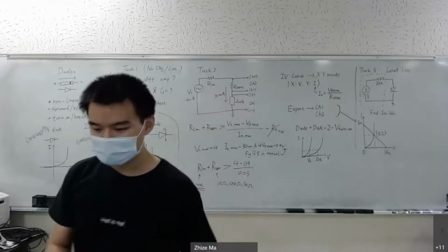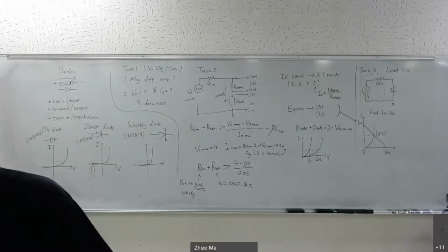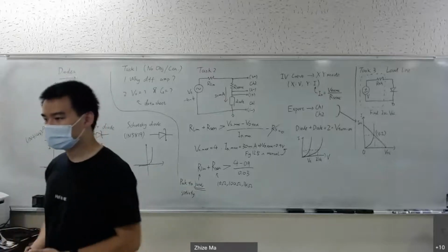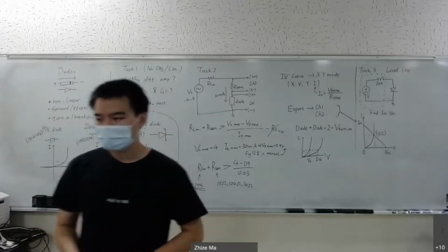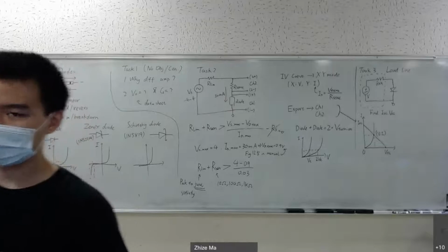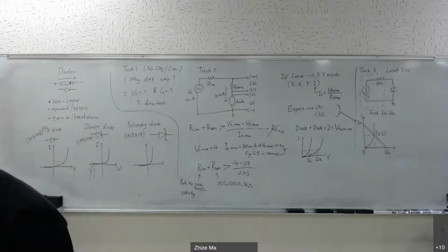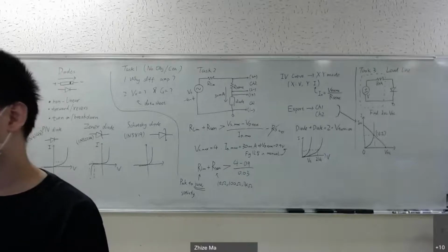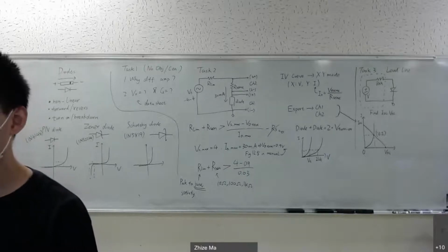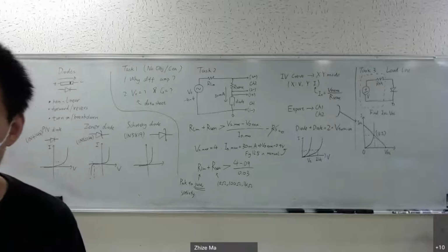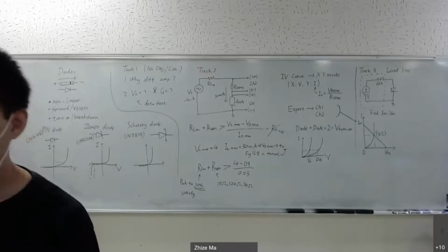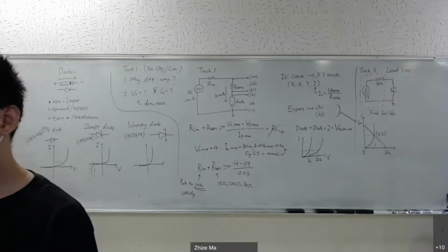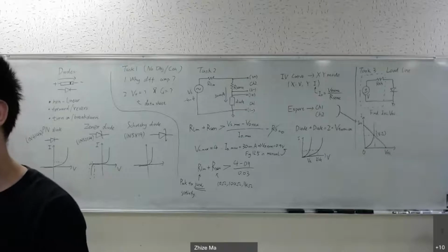The first question is asking why you need a differential op-amp across the sense resistor. One thing I want to let you know is this semester you're using the AD2. The AD2 can directly read the differential signal. But in previous semesters, when you used the benchtop equipment, the oscilloscope on your desk can only read the single-ended signal.